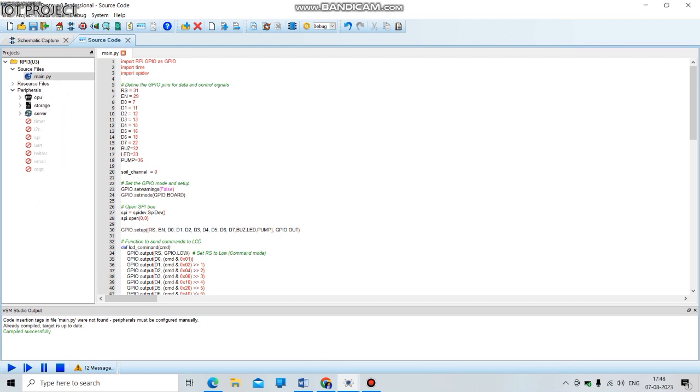Okay, so firstly I have to go down to the coding section. After that I have to go to the simulation section. Firstly I have to import all the libraries, because for accessing the pins of the Raspberry Pi, I have to import this library RPi.GPIO as GPIO. GPIO is basically an alias for this library, because with the help of this GPIO variable, I can access all the parameters in this library.